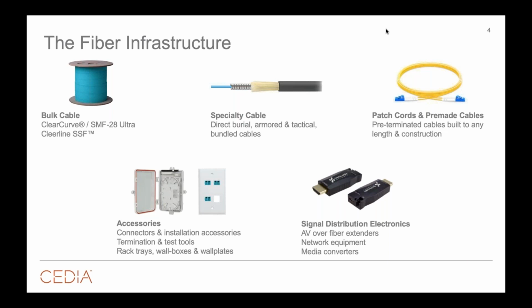And actually, most companies who are starting out pulling fiber cables, they buy pre-mades. And these pre-mades will be 50 feet, 100 feet, 1,000 feet, 5 miles. You can really build these cables to any length where the connectors come pre-assembled. You have pull mesh, they're really strong. I mean, over 100-pound pull rating.